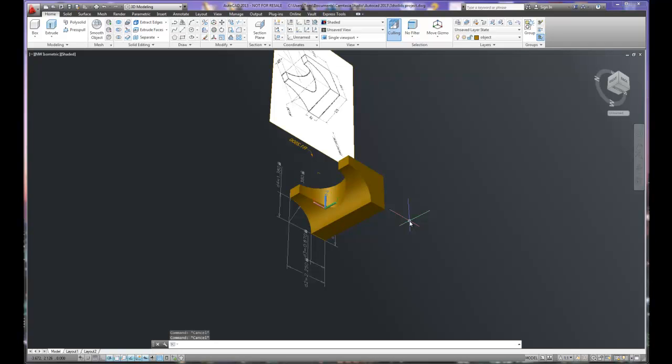So again, a couple of quick review items. We're also going to play with some of the other features here in just a second. Use the extrude tool, use the subtraction tools, shading under view, UCS. I use the 3-point UCS, but you can pick any of the UCS coordinate location tools, the user coordinate tools. That's the difference between it working and not working. And then actually throwing in the parametrics help too. The other things that you could do is you could take all the parametric dimensions, put them on a separate layer so you can turn them off so they'd be hidden in the future. That would be a good task to do.